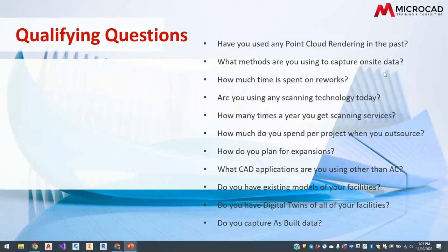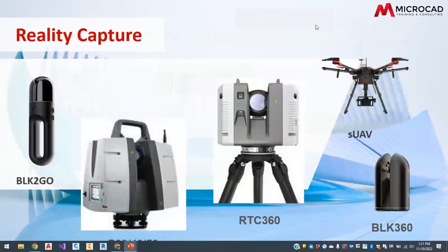What are the differences between the Leica RTC scanner and the P series? Oh, yes, great question. So I'll back up a few slides for that if I can. Here we have pictured in the center the RTC 360, and then maybe the title's cut off, but down below is the P series. The P series has a longer range than the RTC 360, so it can be set up from further away. It can reach higher heights and so on, and it can also do a focused scan where you set the range for it to look at, and it intensely scans that one area.